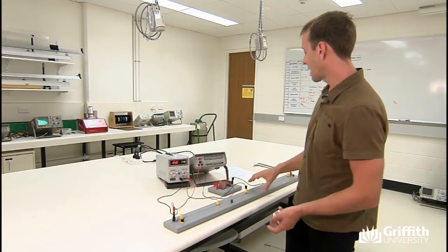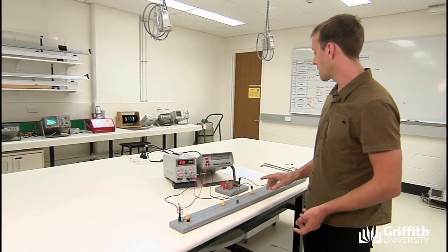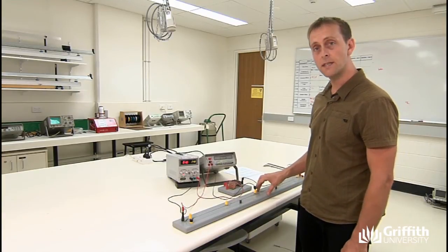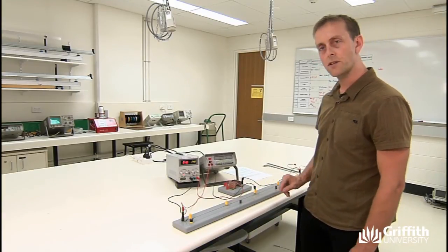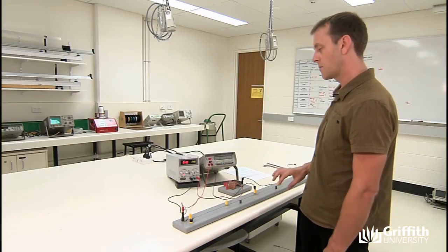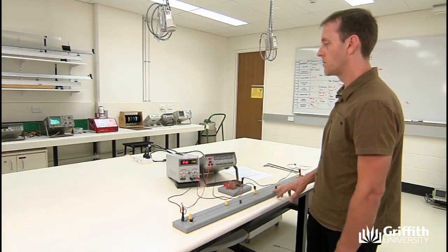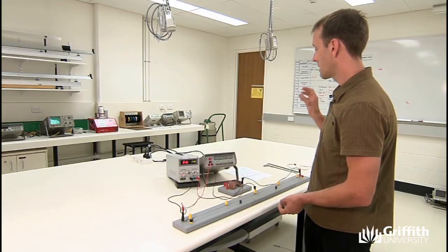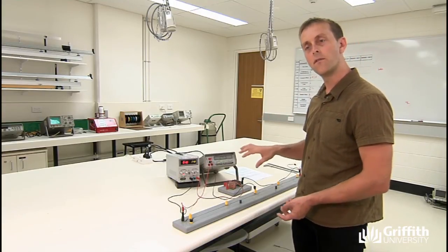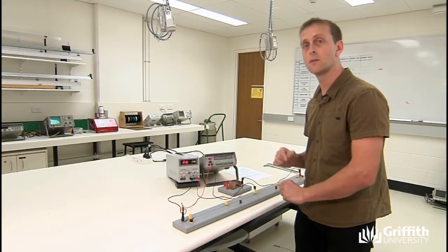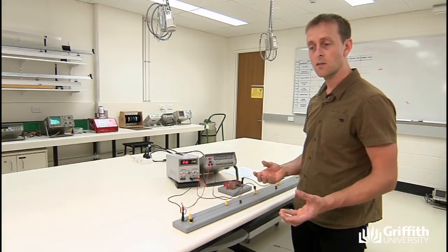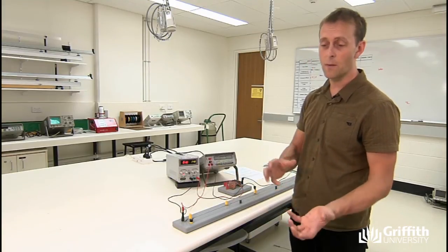Now, the other way you can do it is you can work out, from the dimensions of the stainless steel resistor and the electric field in it, there's another equation that you have that relates the current density back to the conductivity. So you need to go through your notes and work out another way to calculate the conductivity using those things. So then compare that to the value that you got using the reciprocal of the resistivity, and see, they should be the same. So it's always good sometimes to calculate things in two different ways to see if you come up with the same answer.